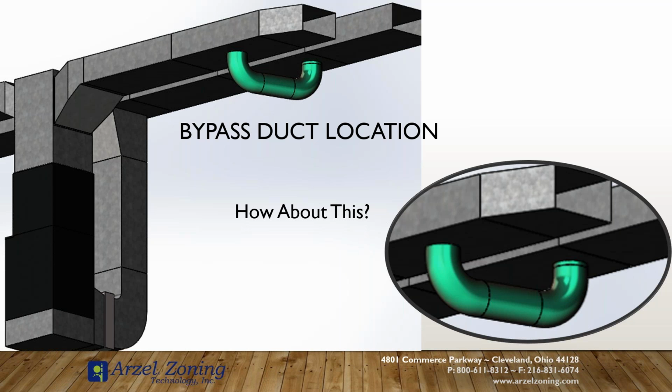And when we come off of those areas, we kind of mess up the airflow in the rest of the system. So your bypass duct, whenever possible, should be installed on your main trunk line itself before your first reducer, about 12 inches before your first reducer, and hopefully that's about 8 feet away from your plenum. And then on your return side, it should be about 8 feet away from your drop.